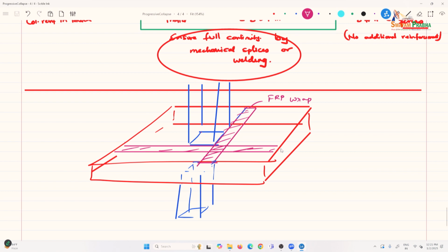They do this even in regular flat slabs, for example, to enhance the shear strength. I'd look into what they do in enhancing the shear strength, and use principles very similar to that. These FRP wraps work very well in tension. Even in columns, you could consider wrapping the entire column with FRP wraps, FRP sheets basically. Anybody's got experience in that?